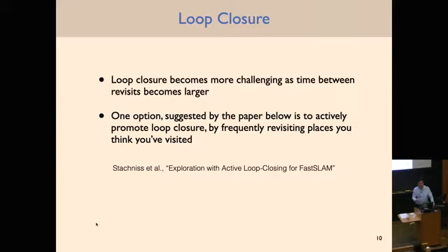Yeah, I was going to ask, are there instances where you're more likely to think you were visiting somewhere, but you're actually in a new location? Yes, that is also possible. If you have locations in the environment that look very similar, that could potentially mess you up quite a bit. You could think you're visiting some previously visited location, but really it's some other place that looks very similar, and then you get pretty bad looking maps.